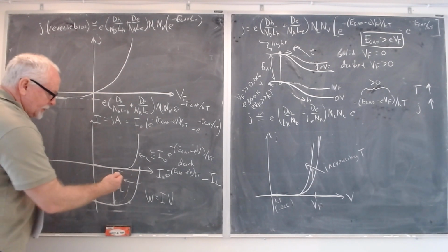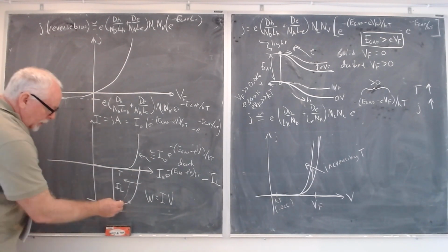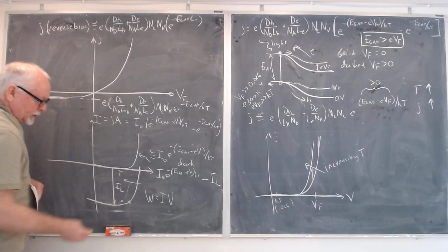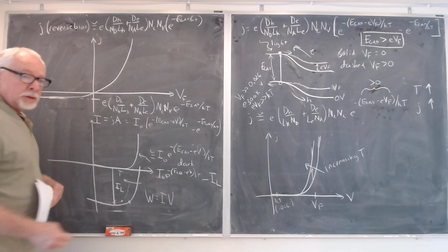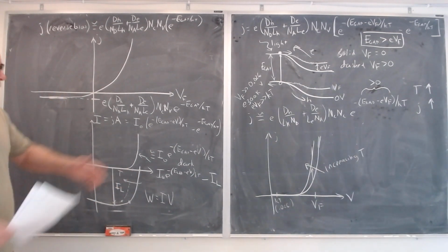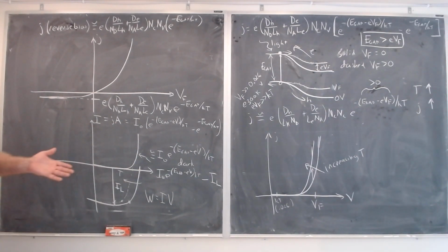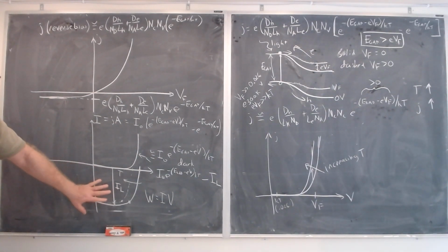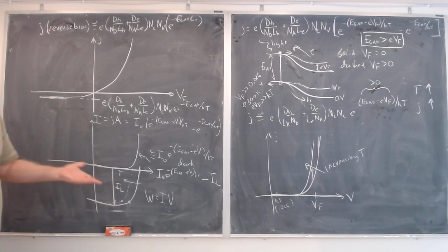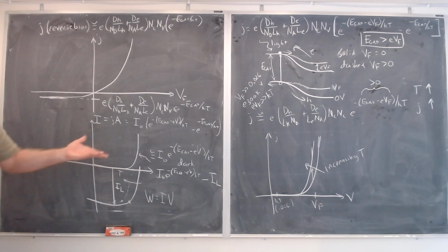As temperature increases, that's going to go that way, and so the maximum power point will get smaller. Because of all this and how it works, as the temperature increases, solar panels produce less power. And you can see that directly here from the equations.